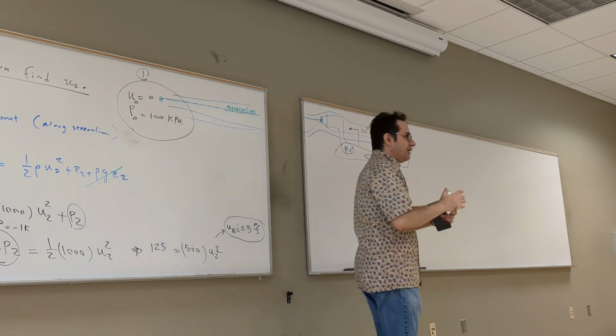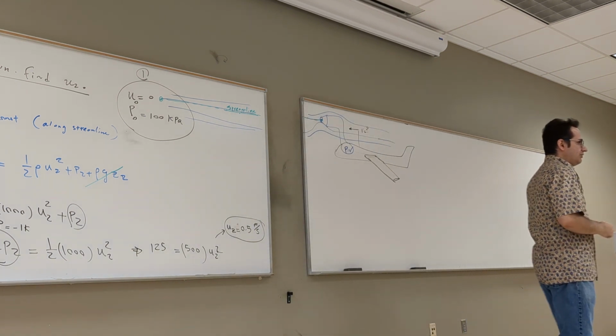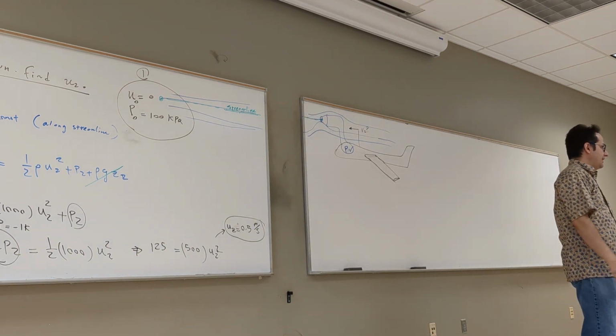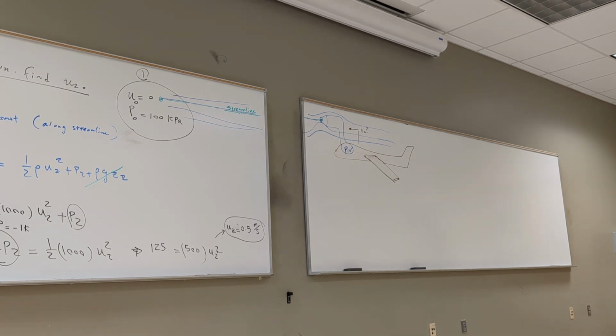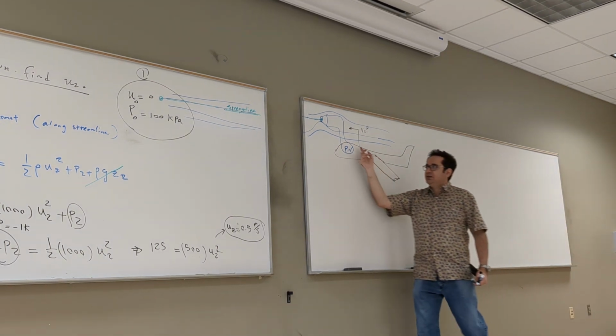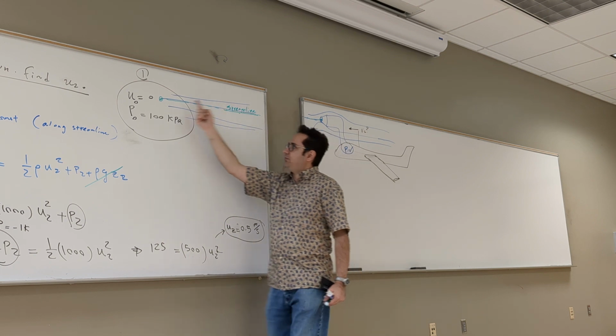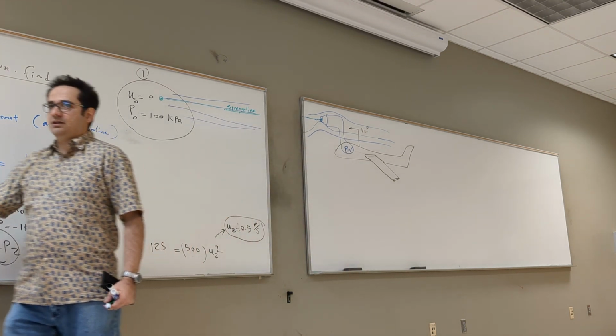If the speed is high, the density may change, compressible flow. So that equation is not valid. Again, there exists a Bernoulli equation, but that's different for compressible flow. It's more complicated, it's longer. The equation here is for incompressible. So if the speed of the aircraft is very low, this equation from the tip of the pipe all the way to infinity is perfectly valid.